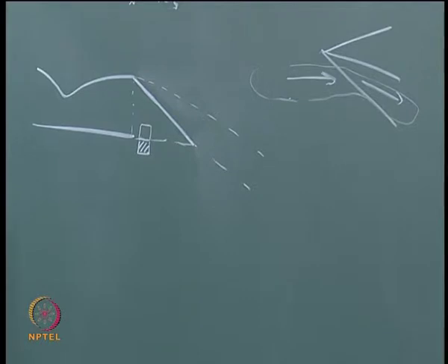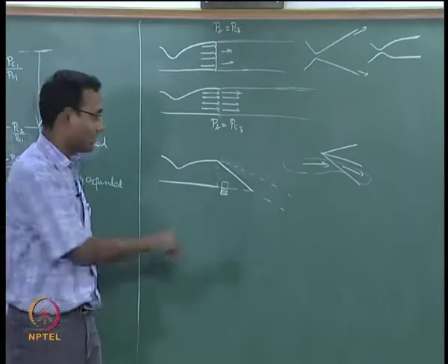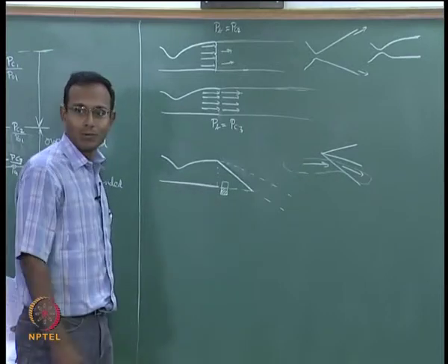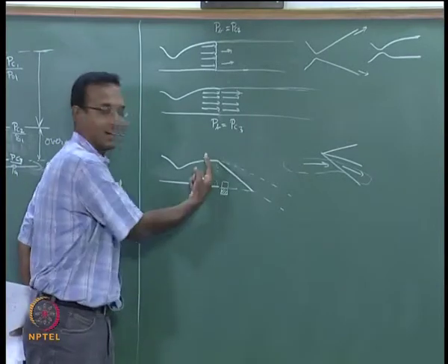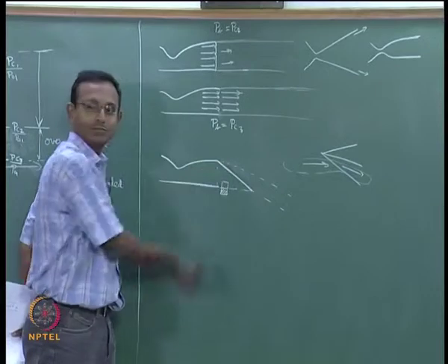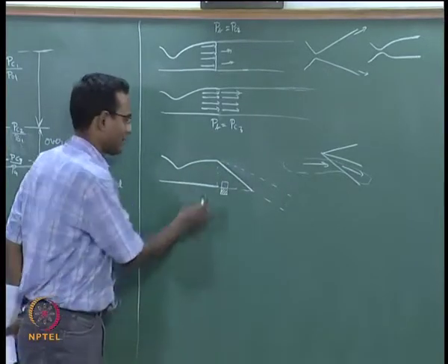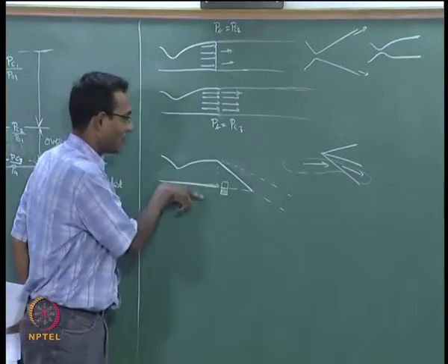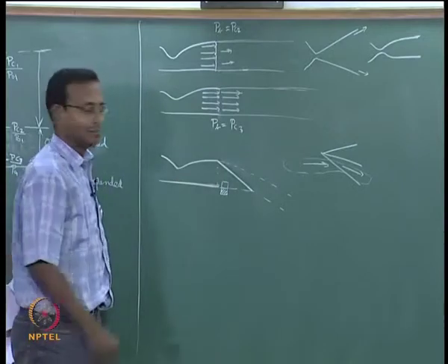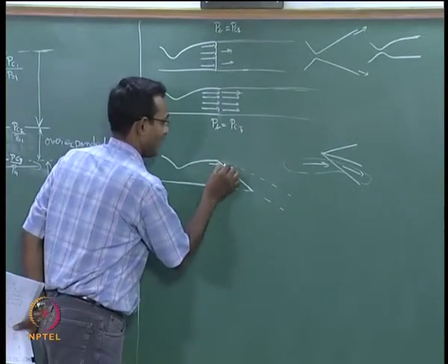What will happen? Naturally this fluid element will push that fluid element up. Along that border there is unequal balance, right? One guy is pushing less, other guy is pushing hard. Then the boundary will move. What does that mean? This last fluid streamline is going to turn inward, we said this fluid element turns this way.